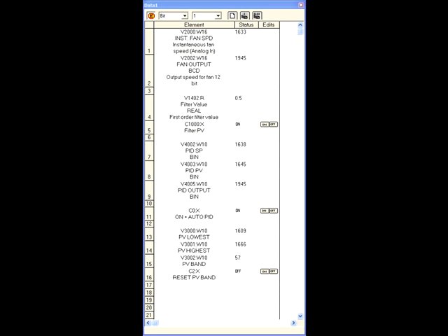Now that we've covered the ladder logic code, we'll look at a data view window which holds the important controls in this program. You could use a CMORE to do the very same thing, but the data view allows us to do pretty close to the same monitoring and control. The first value is V2000, which is the analog input raw value.